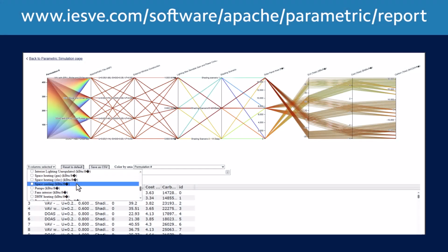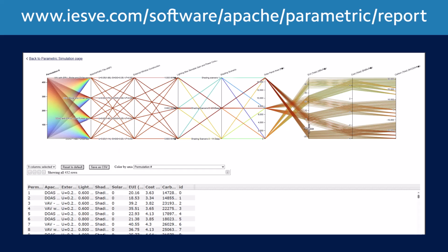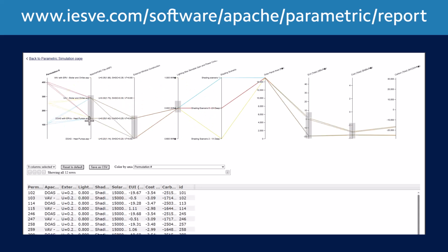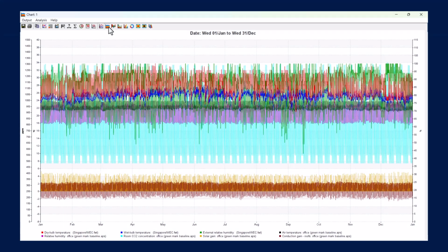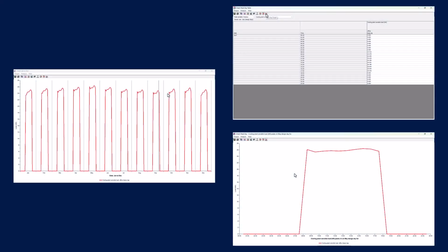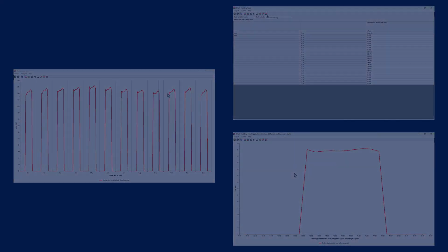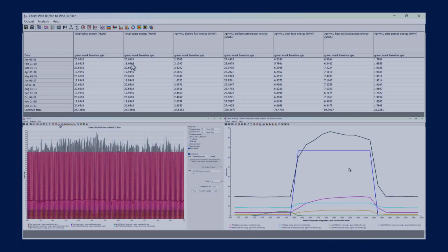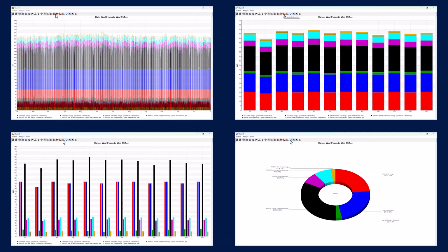The VE also includes a parametric tool, which makes it quick and easy to undertake an iterative process for design improvement scenarios and the assessment of different ECM combinations. Accurate decision-making lets us confidently justify innovative strategies for energy savings. The IESVE facilitates baseline versus proposed comparisons. We can implement value engineering and use reports or tables, graphs, and charts to clearly demonstrate energy improvements and secure the targeted points for our Green Mark project.